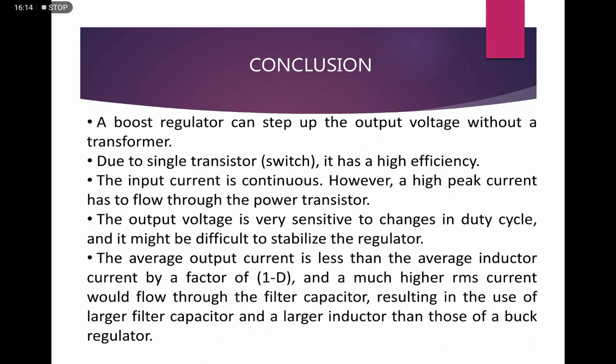The output voltage is very sensitive to changes in the duty cycle. Obviously, from the equation we know that your output voltage only depends on the duty cycle and Vs, so any variation of these two parameters will affect the output voltage.